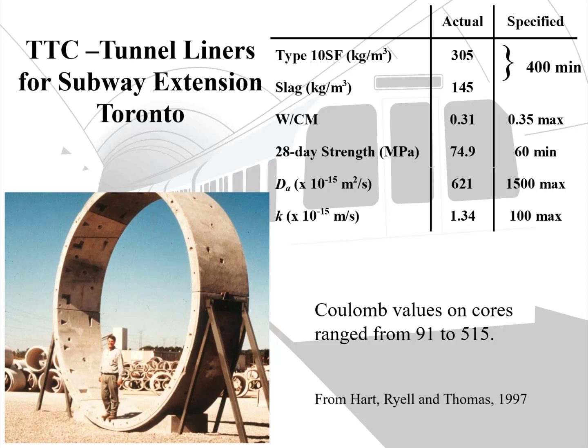I know in Ohio, slag ternaries with fly ash are used, in other areas too, and you can use it with limestone as well. We use it on high performance, 100-year service life tunnel liners, such as one ring of a tunnel liner, 7-segment precast tunnel liners.